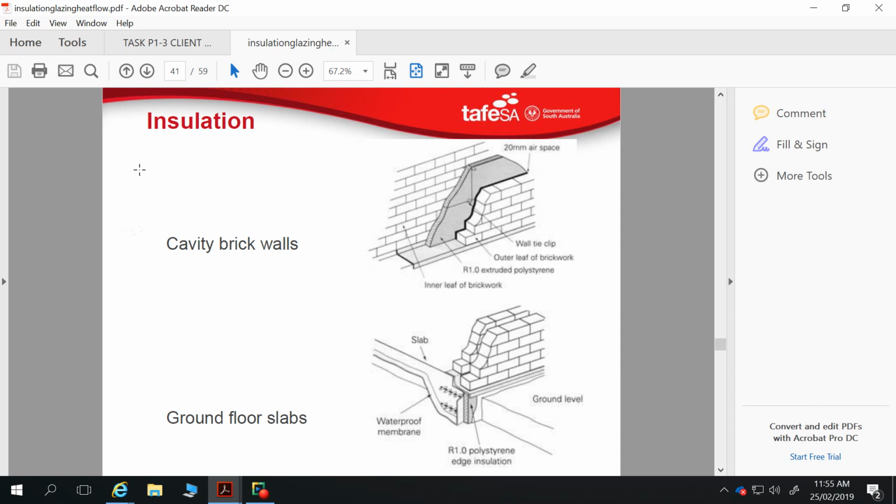When you've got that cavity in between, then you can do something like this cavity board insulation in between the two, and your brick ties go straight through that with little retaining clips on that. That works. I guess you're getting your benefits of reverse brick veneer in that you've got masonry on the inside of your house providing that thermal mass, but then you've got your benefits of a brick veneer house, which are an external skin of very durable materials on the outside.